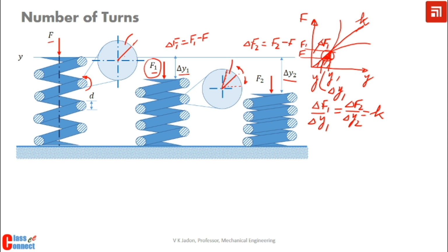And what is the strain energy of the spring wire? We can understand this if we plot the twisting moment versus theta, that is the angle of twist curve. Within elastic limit this curve is also a straight line, that is MT and theta, where theta is the strain within elastic limit.